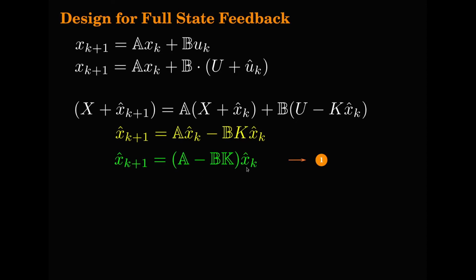So if k tends to infinity, so as time progresses, we would like the deviations in the neighborhood of the operating point to ultimately go to 0, and finally the values will tend to these uppercase values. So as k tends to infinity, x(k) hat will tend to 0, the deviations tend to 0, and what will be left off in this original state equation is only the steady state value or the nominal operating point values.